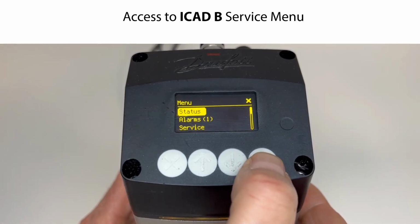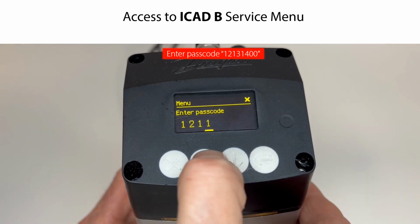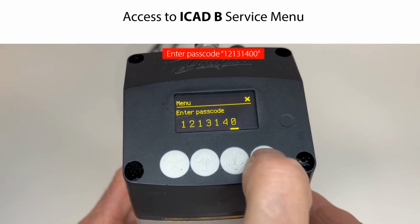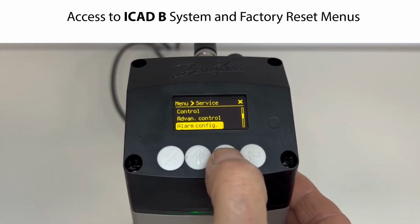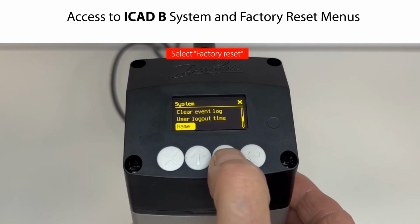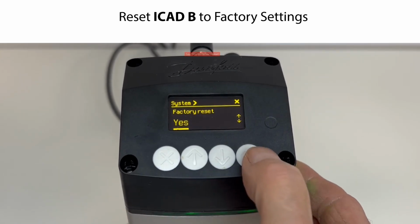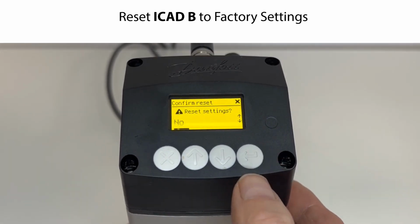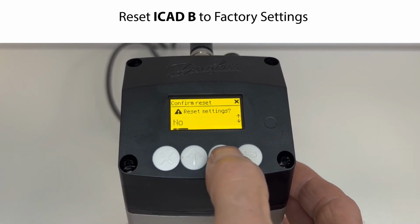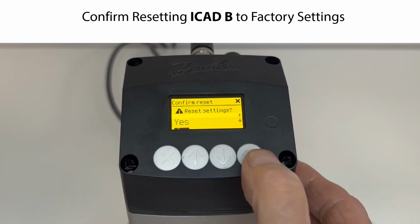Press enter and scroll down to service, then press enter. If requested, then enter the service passcode as explained earlier in this video. Scroll down to System, then press enter. Scroll down to Factory Reset, then press enter. Press the arrow down key to say yes to the factory reset, then press enter. Scroll down to yes again to finally confirm the factory reset.